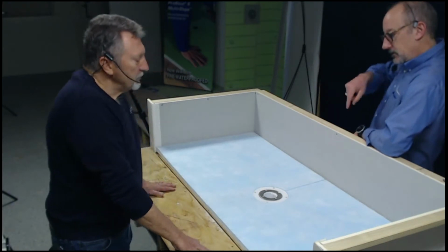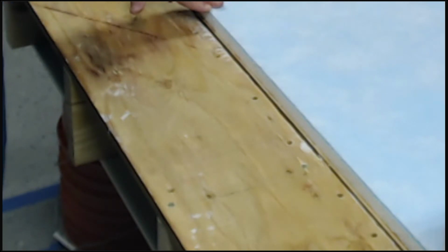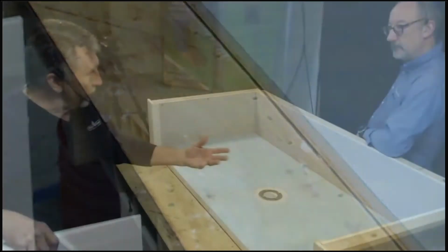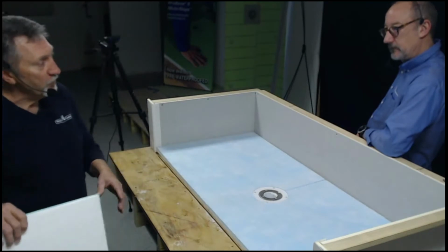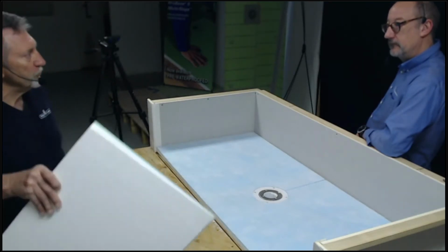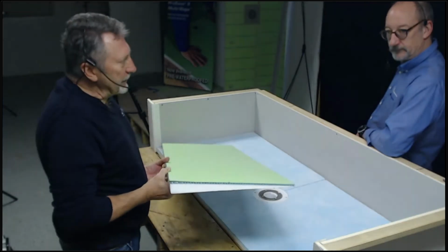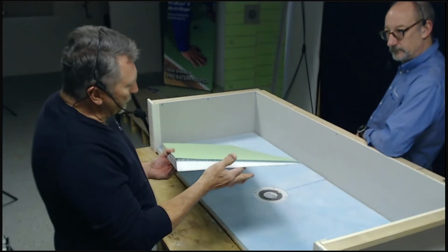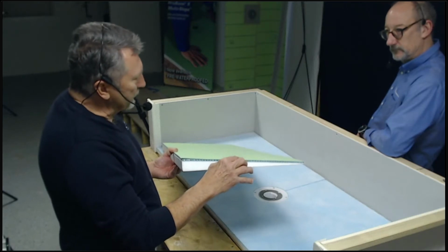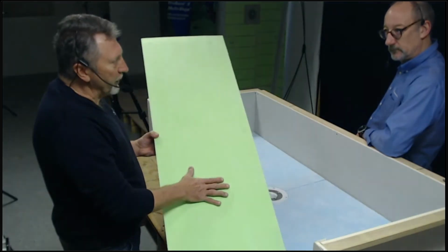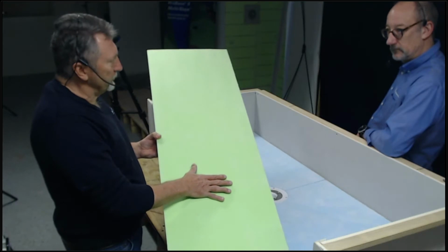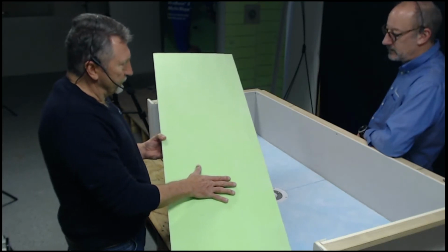What about the transition out here? With our 3260, it's 1 1/4 inch tall at the perimeter. So you're going to have to either build up your dry space with either mud or backerboard to get a nice smooth transition, or you can use Noble's new barrier-free ramp. Again, this ramp is made out of the 3-pound foam with a 1/4 inch honeycomb on top of that, and we pre-applied the waterproofing to the top of that. Makes it easy.